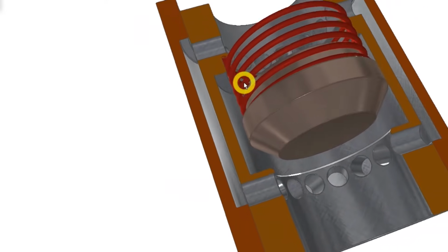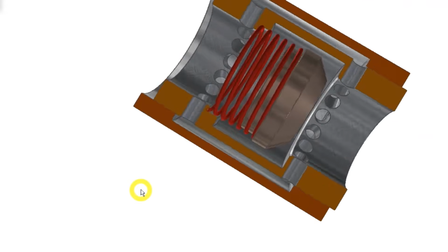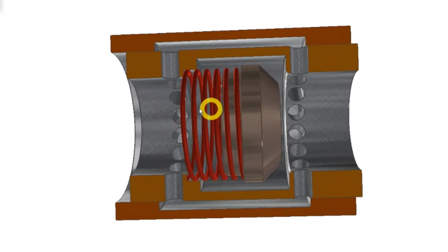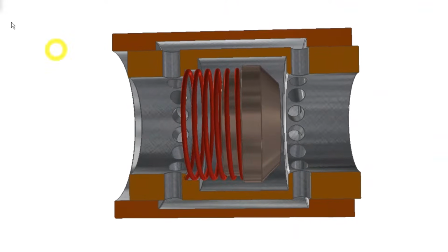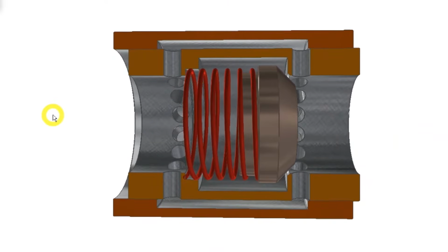So looking at the way the valve is drawn right now, you will have full flow from the right to left, but if the direction of the flow changes, the valve will close and force the liquid through the adjustable nozzles. This is the symbol of the open return choke valve. The choke valve itself is the same, but you can see a bypass with a non-return valve next to it.